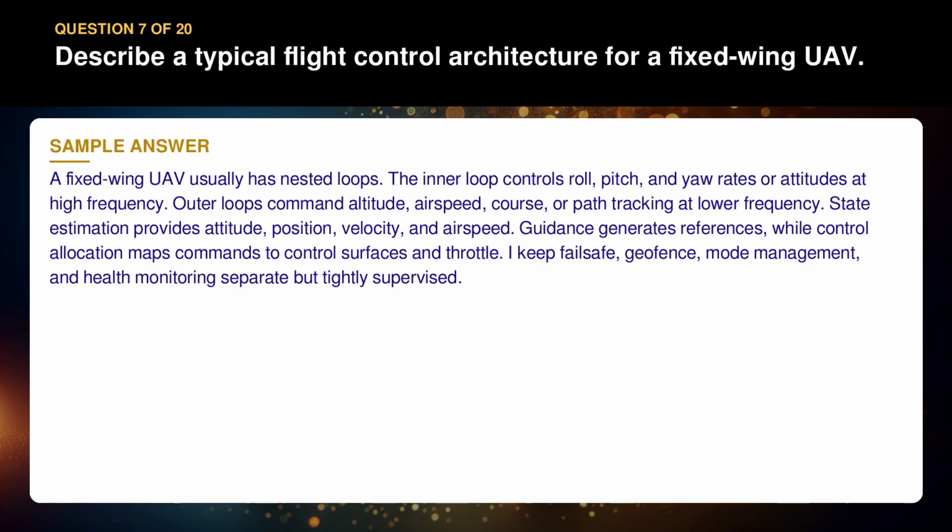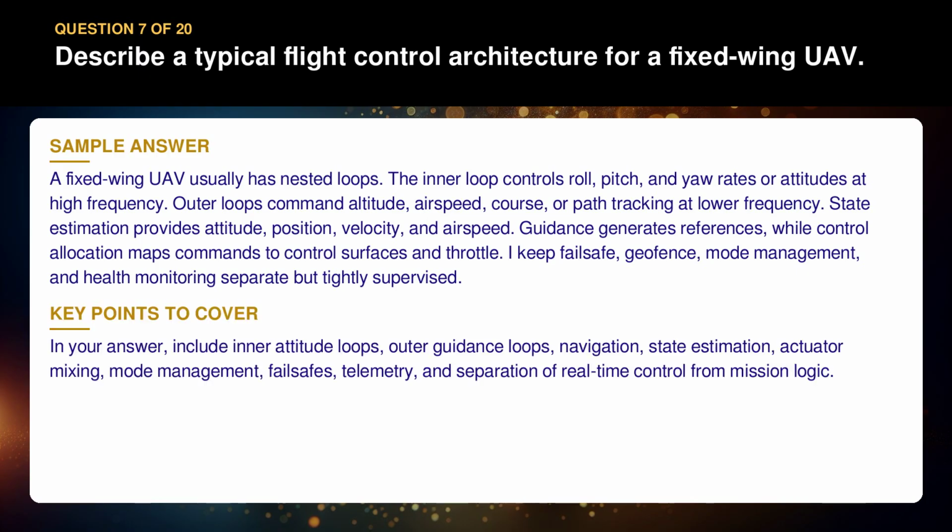I keep failsafe, geofence, mode management, and health monitoring separate, but tightly supervised. In your answer, include inner attitude loops, outer guidance loops, navigation, state estimation, actuator mixing, mode management, failsafes, telemetry, and separation of real-time control from mission logic.